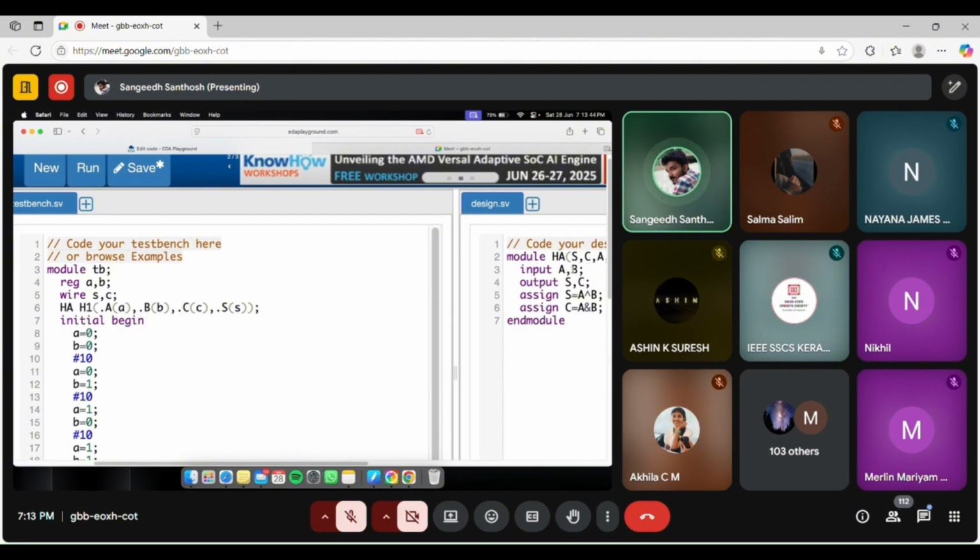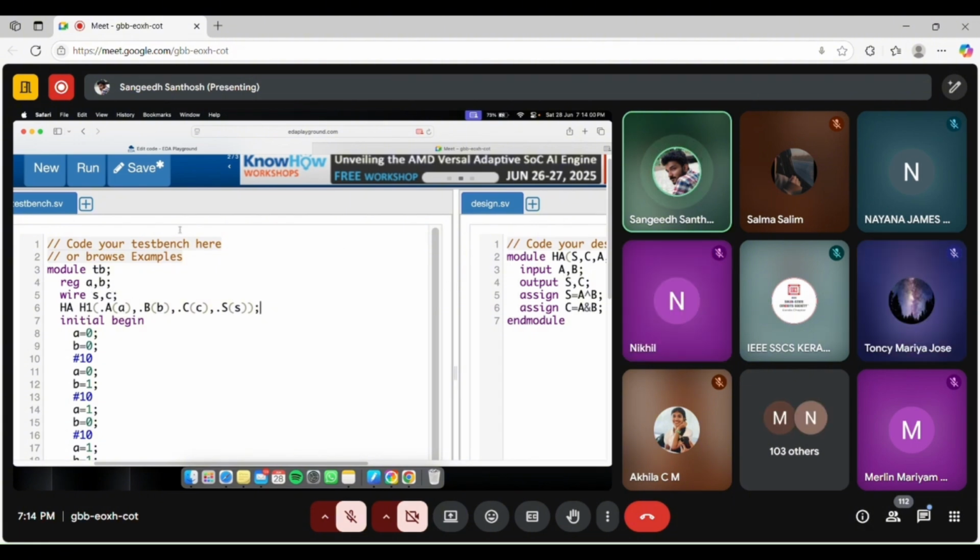So those will be acting as a register in this test bench. So this A and B is not same as this A and B. That's why I've written it as capital and small letter to understand these two are different. How we map this to this, I will explain. So first we need to understand is whatever input we are putting in the design, that will be a register over test bench. Okay. Then outputs will be wire, same as in the design part.